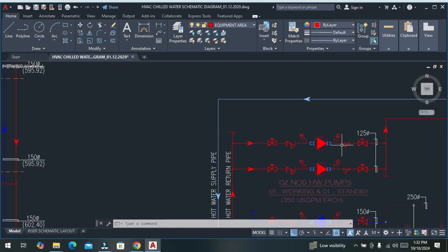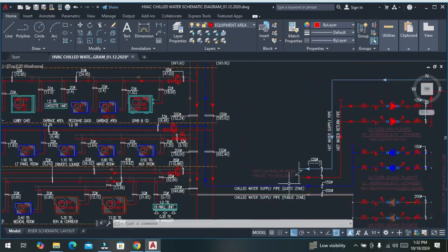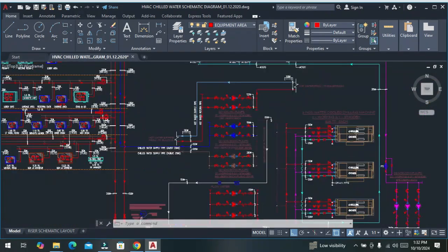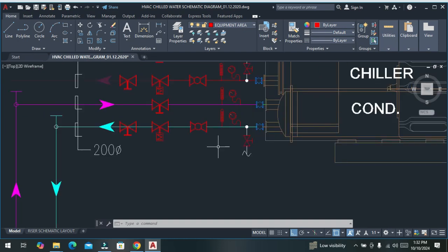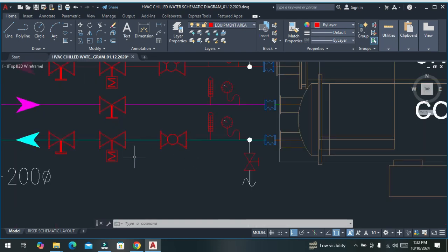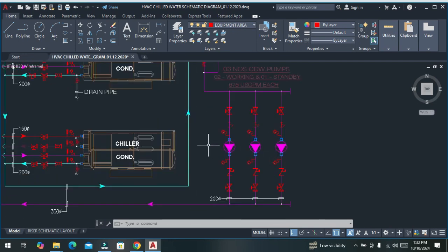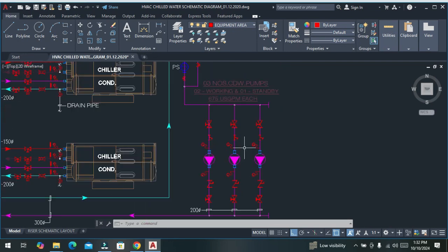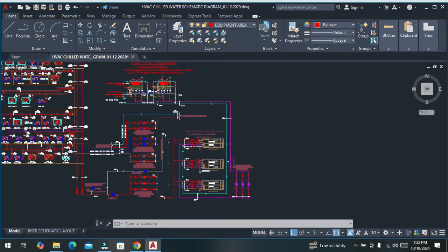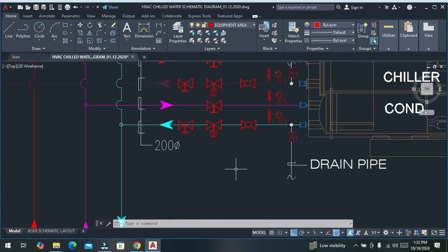Let's say the outlet temperature of this condenser becomes 27 degrees Celsius, then the cooling tower fan will automatically turn off. But the circulation pump, we have to keep running, this condenser circulation pump. So in this process the condenser part works.